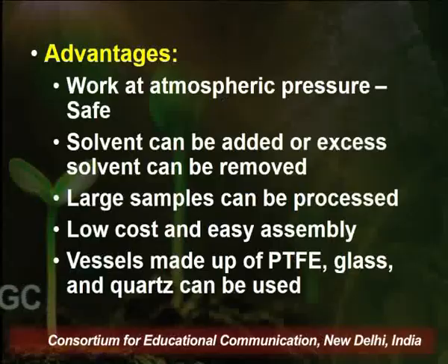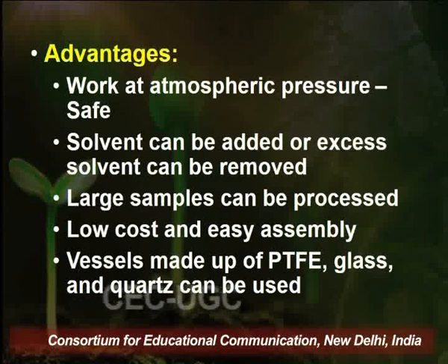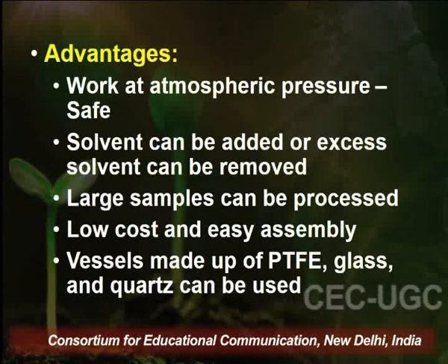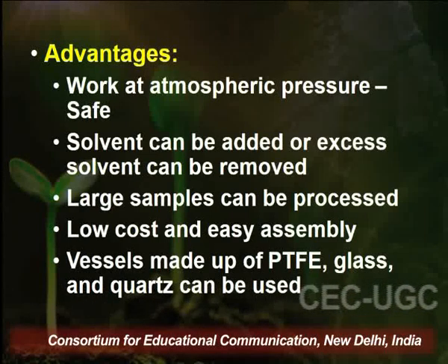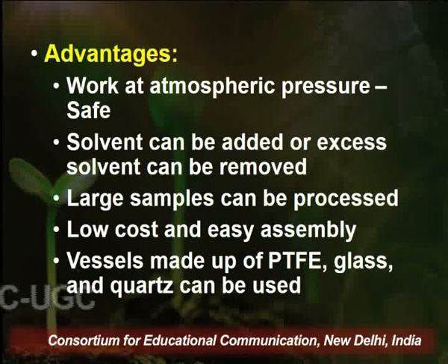Now there are certain advantages of open systems. You can work at atmospheric pressure, and therefore they are considered safe because no higher pressure is there, so no danger of explosion of the vessels. Solvents can be added or excess solvents can be removed during the extraction. Large samples you can process with the open extraction vessels, but again you have to process them in batches. Since they are very simple to design and simple to set up, they have a low initial cost, and they are quite easy to assemble.